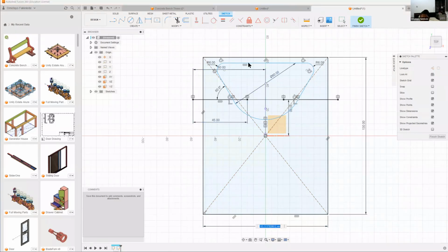Another thing I might be interested in here is I can just decide to make a hole inside this place, and I can make this like a laminar that has a hole drilled into it. I don't need to do anything really, because if I extrude only the outside one, there will be a hole there made by the one that is inside here. But let me just do that for you to see.